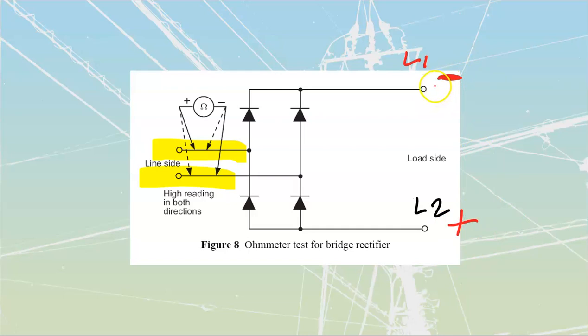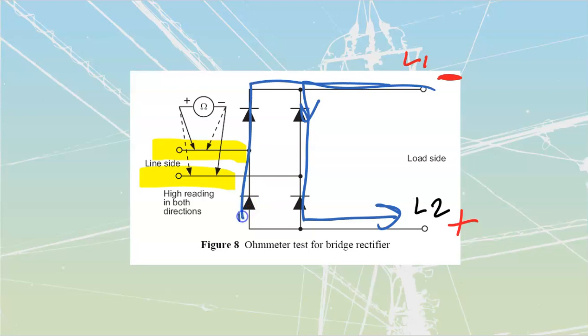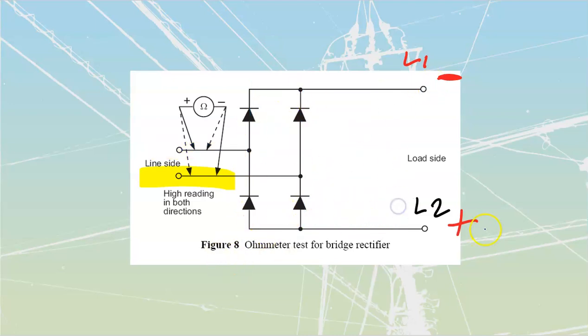At that point, I'm going to see that I would be able to pass current through a forward biased diode. That one's got a negative, it's going to be forward biased. This one's got a positive, it's going to be forward biased, and boom, I've got current that can travel through there, as well as a second parallel path, just in case the one short circuit wasn't good enough. I've got 2 short circuits over here, so I can get a dramatic explosion and the smoke gets out and things like that. It is not something that you want to go and see. So make sure when you're hooking these things up, you do not connect it backwards. If you connect it backwards, guaranteed destruction of your components and a short circuit.